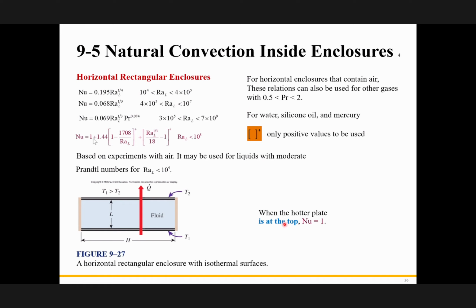Again, as we mentioned, if the top plate is hot, the Nusselt number is equal to 1. Okay. Remember, this is only pure conduction because the cold air is sitting here, there's no energy to move it up. The hot air has been sitting here.